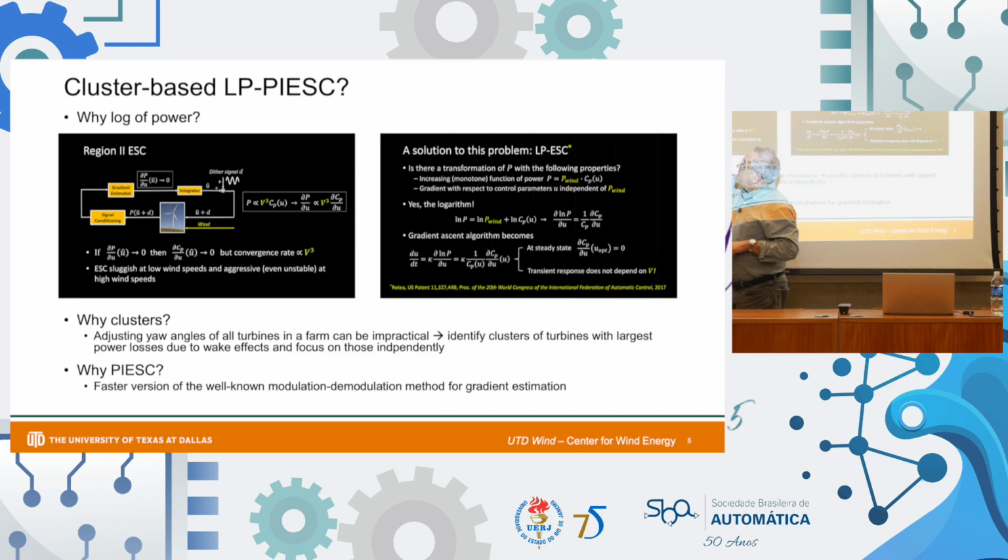And then this machine produces power. We do some signal conditioning on the power. We extract the gradient. And the objective of the extremum seeker is to drive the gradient to zero, because that's the necessary condition for optimality. That's why typically this is just an integrator.